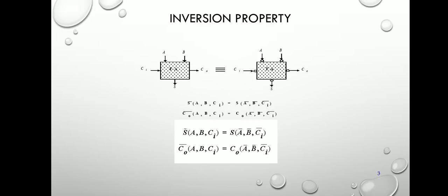So an adder is a digital circuit that performs addition of numbers. Mostly the adder has a half adder as well as a full adder. In the case of the full adder, it adds 3 single bit inputs and produces 2 single bit outputs. It is very useful when an extra carry bit is available from the previously generated results. So here this will add together the 2 bits and give the result as an output. These bits being added together are called addends, and adders can be concatenated in order to add together two binary numbers of an arbitrary length.